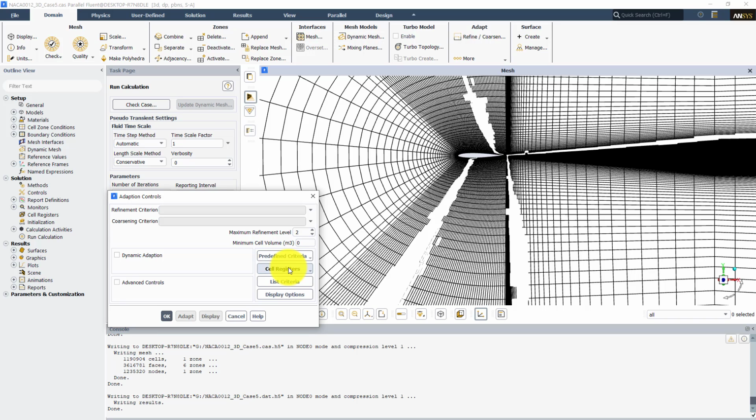This is basically the Manual Mesh Adaption panel, traditionally used for mesh refinement and mesh coarsening. We can also have 2 registers or more. A register is basically a collection of some mesh portion. For a multi-phase simulation, let's say with air and water, we can initially have some level of air and water in the domain, so we can also use a register to define the boundary conditions and initial conditions for the water and air level in the domain. And the third application is partitioning.